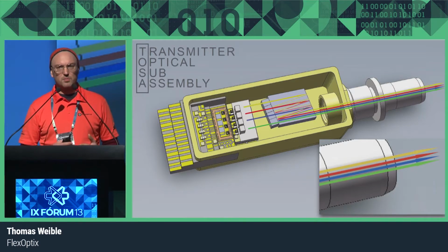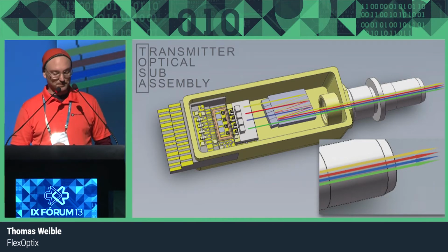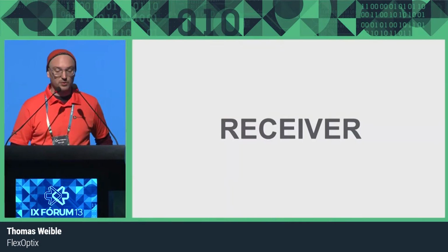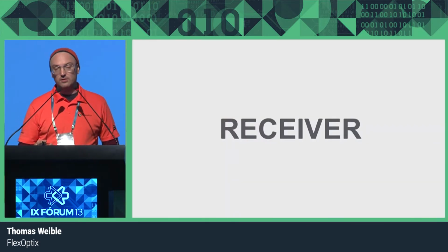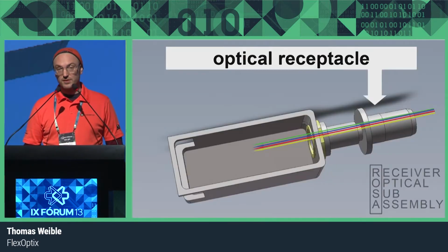All 4 colors are combined within that filter block, and the signal is bouncing back and forth, always at the dotted glass at the edge of the filter block. So now we are at the filter block, getting out on the receptacle on our fiber, and now the signal is on the fiber, and we have to hit the receiver.